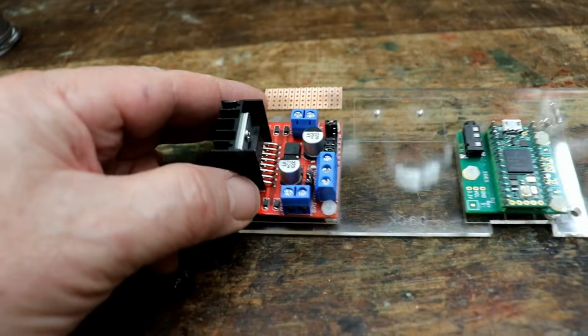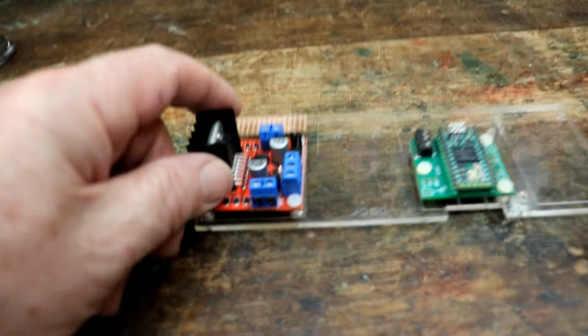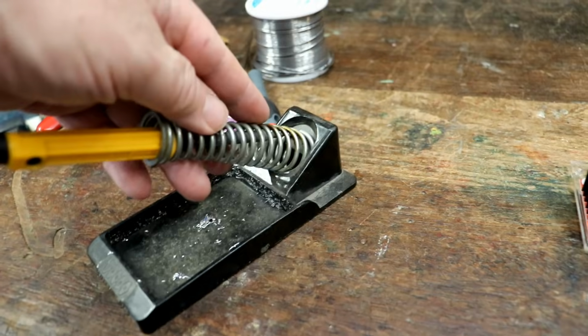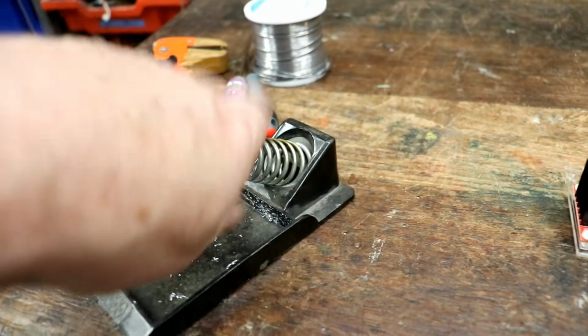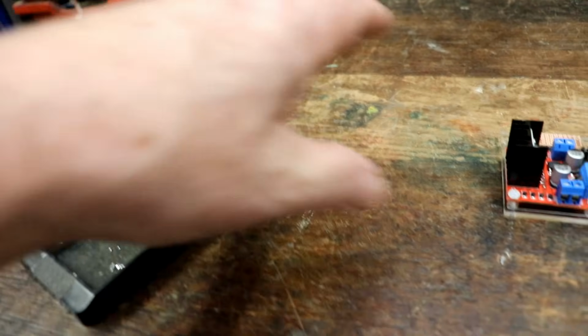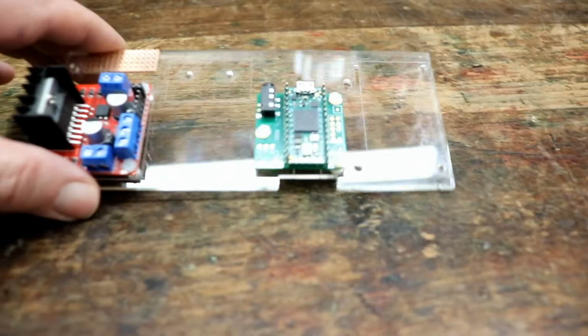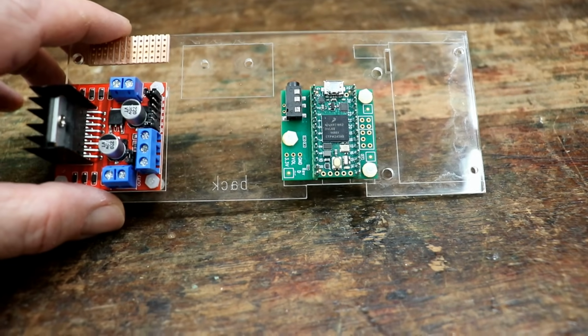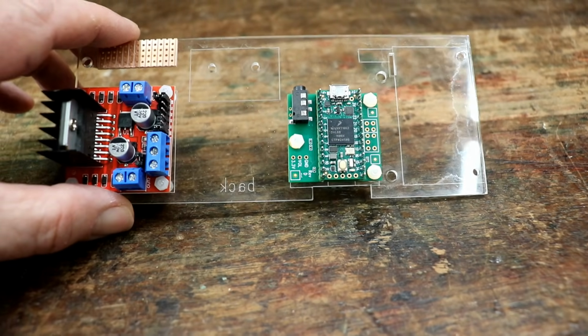Now what I'm going to do first of all, and I keep meaning to say, when you're handling electronic items like this, sensitive little things, it's always a good idea regularly just to touch something that's earthed. The soldering iron is earthed, so I just regularly touch that in case I've got charged up with static from clothing or whatever else. I'm going to connect all the grounds up first, 0 volts, with the black wires, and then the reds.